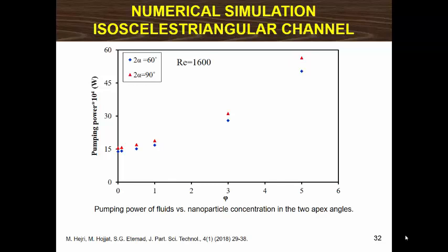Experimental results of our previous work done by Farajollahi et al. that I explained before were used. Input of the ANN model was nanoparticle volume concentration, Reynolds number, nanoparticle thermal conductivity, and Prandtl number. Results indicate that the ANN model predicts experimental data with a very high accuracy. The ANN is then used as a meta-model for evaluating the objective functions for optimization. Nanofluid concentration and Reynolds number were selected as decision parameters. The Pareto front was obtained.